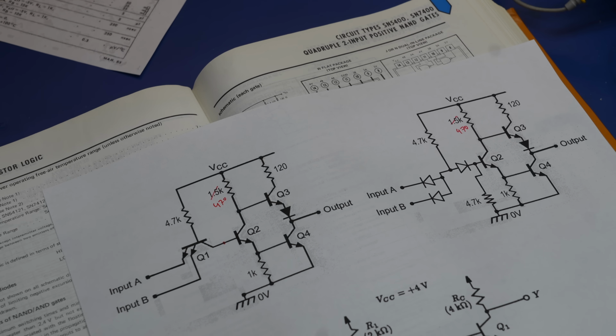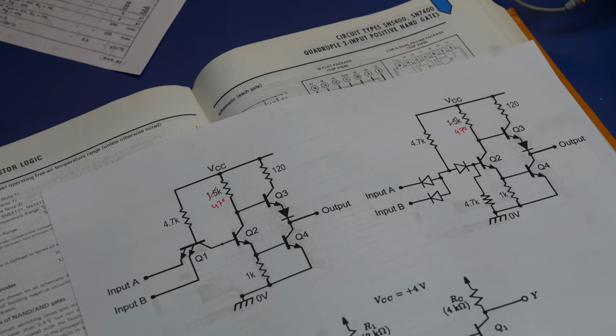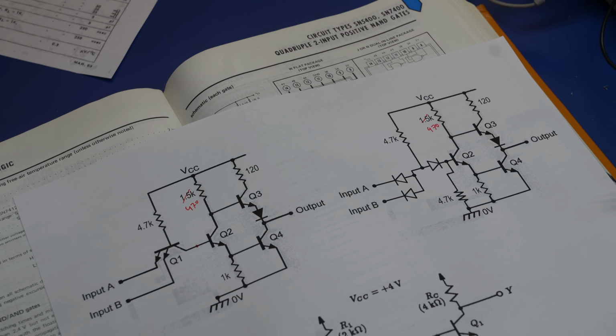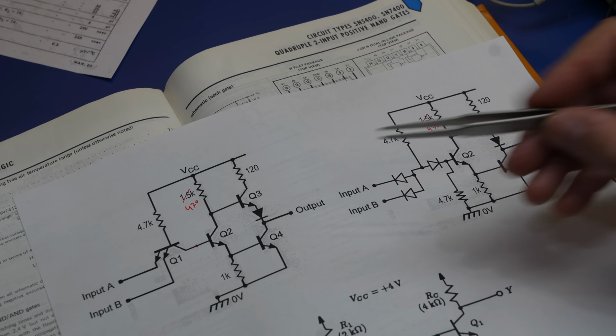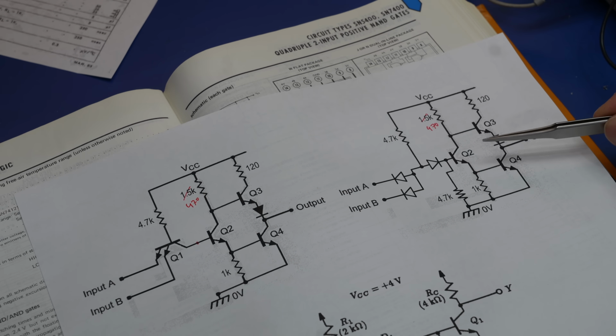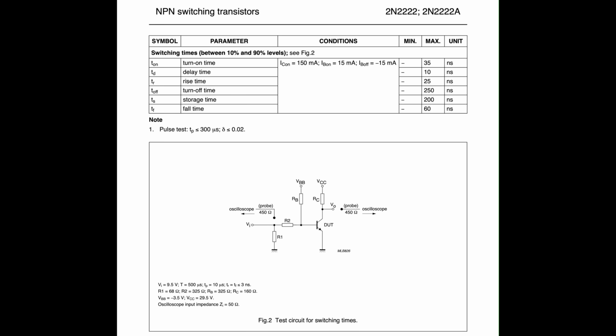But the gist of it is that for a transistor used in a switching application, which is usually driven fully on until it's in saturation, the switch off time is much slower than the switch on time. That's because you have to evacuate the charge buildup in the base. It's a property of bipolar switching transistors that you can easily spot in the spec sheets. T on is much faster than T off.